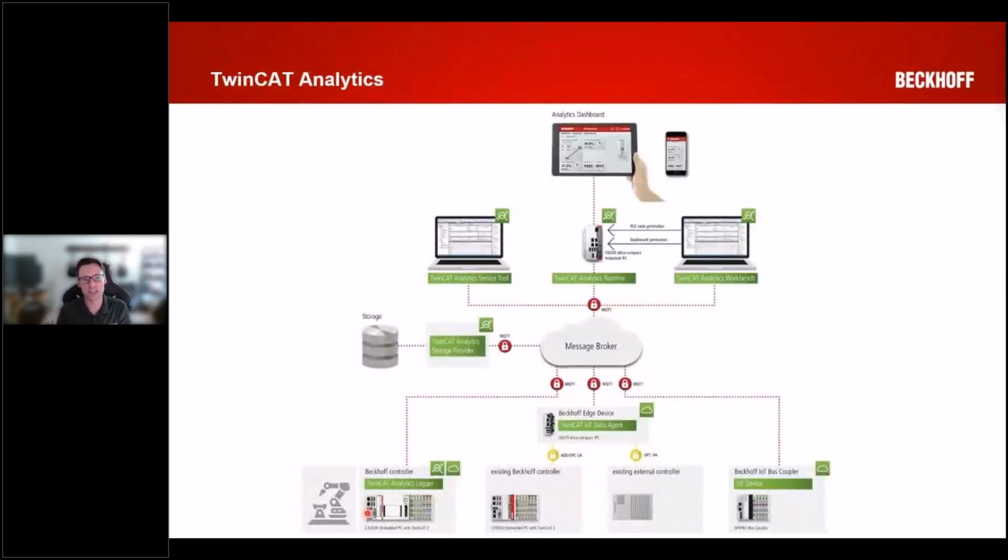So for every machine, you're going to need an instance of that license. Now, that is also the lowest cost component of this whole picture. It's a really low cost adder license. And again, it's typically already installed with your TwinCAT runtime. It's just a matter of enabling it, ticking those boxes to select which signals you want to log.